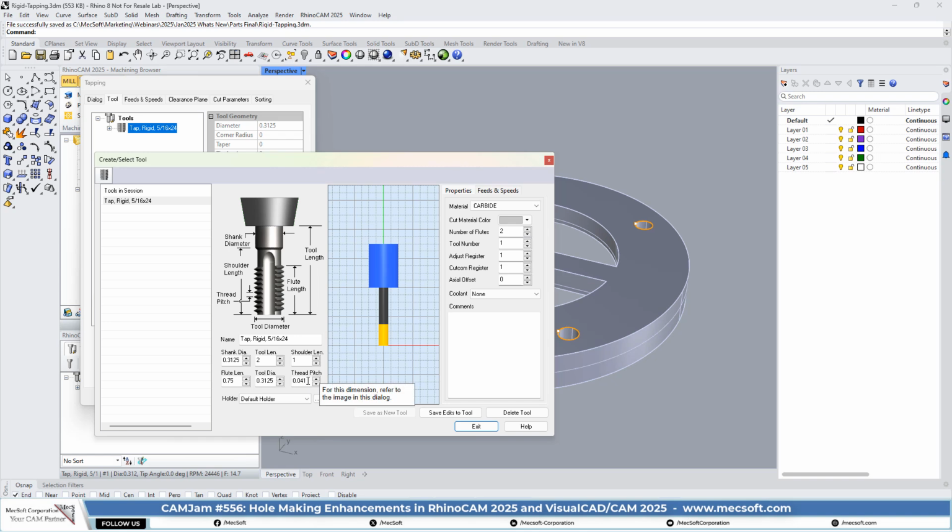And this is the critical part, as we did in thread milling and looked at the thread milling tool, the tap tool. Your thread pitch is the most critical dimension that you need to make sure you meet. Obviously, your tool diameter, etc., needs to match the threads that you're tapping. But that should all be taken care of if you buy, what is this, a 3/16 or 1/8 tap tool or .3125 tap tool. All those dimensions will be in your spec sheet for the tool itself.